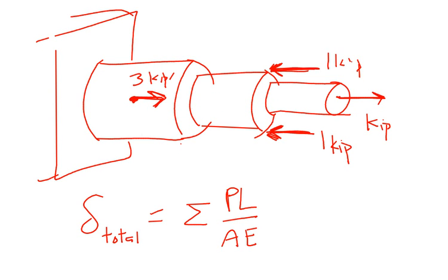That's a change in everything, right? You see these one kip forces being applied there. So that's a change in internal force. That's also a change in area, and it's a change in material. So I've got a change in all three. So this is one segment. That's my third segment. And then, of course, I keep moving until I get to the very end, and that's my fourth segment. Okay? So in this problem, there are actually 4 PL over AE terms.